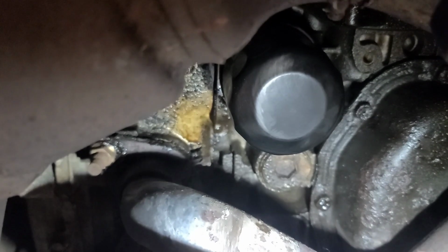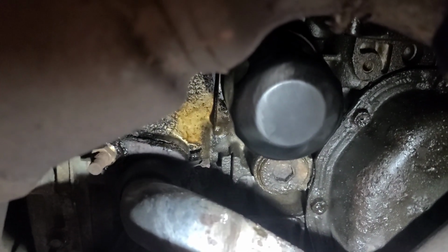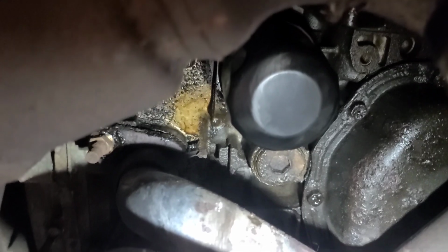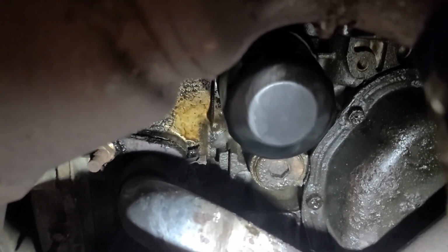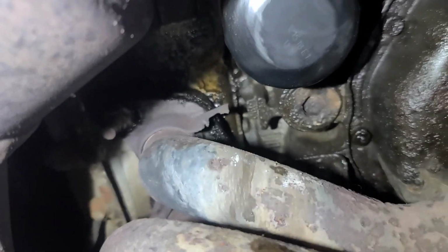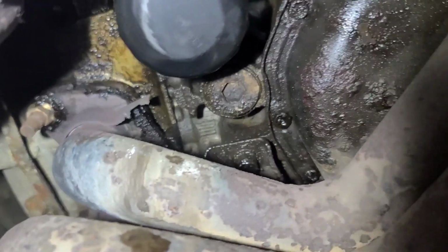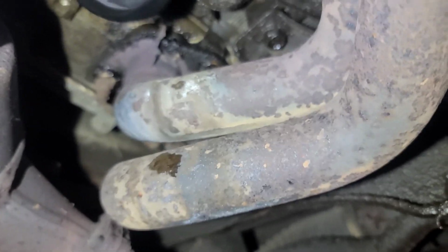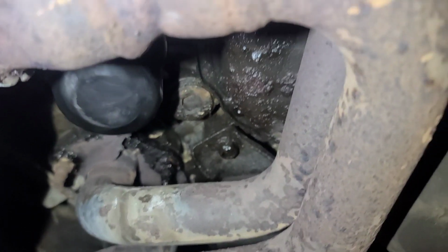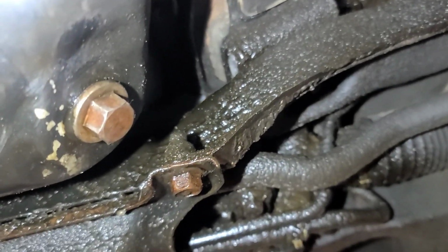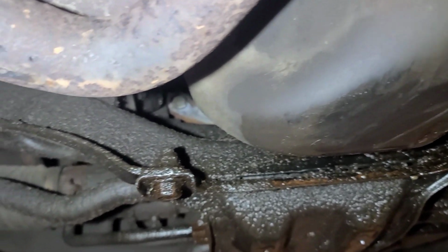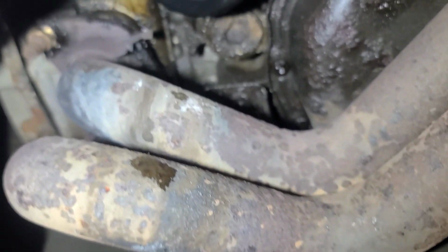So we're having a look underneath here, and you can see up beside the oil filter there's a drop of oil from the head gasket surface, and I think it could be leaking there. I think that's a known condition. So we don't want to spend too much money on this thing because it's got high mileage and obviously oil leaks. That O2 sensor won't cause a startability problem in my opinion, so we're going to hold off changing it. It's actually an air fuel ratio sensor and it's almost 400 bucks. I am changing the oil because it's down 1.5 liters and it's very dirty, but you can see the oil's been dripping here.